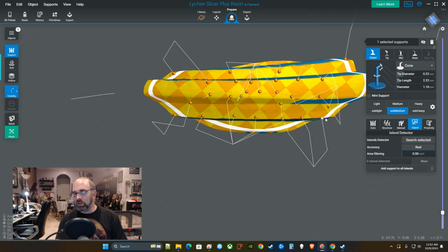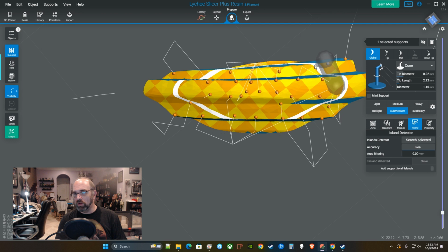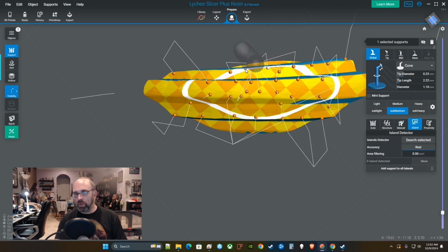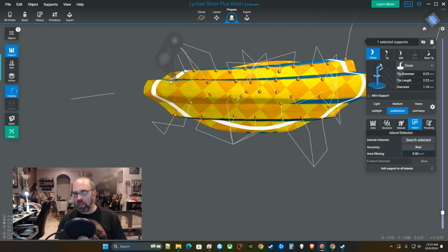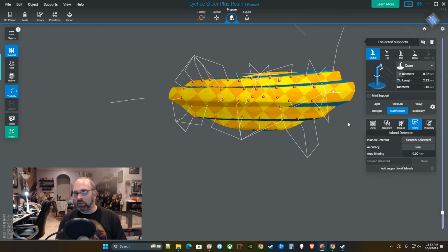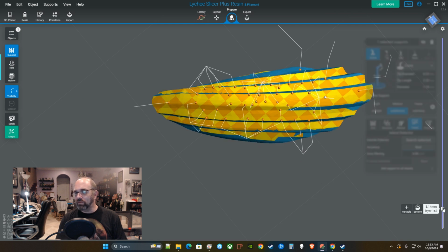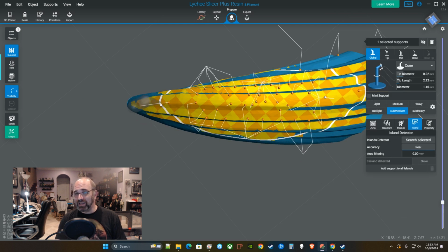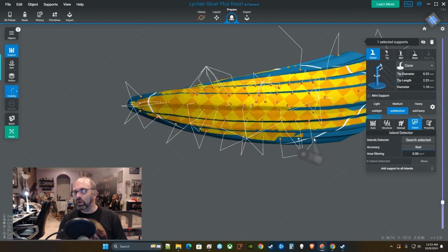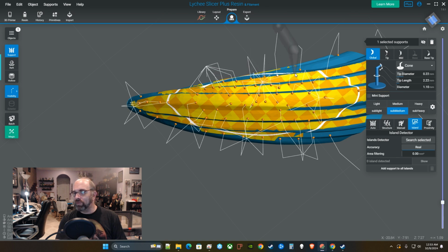And you'll notice that white line that kind of follows your mouse. I want you to pay really close attention to that. That is your slice line. You can technically use that as a guide to place supports. In a lot of cases I will actually use its direct curves to create my support curves. This usually leads to the supports being very well distributed, and it leads to the part being very well supported with very little damage, and that's because of my choice of support tips.